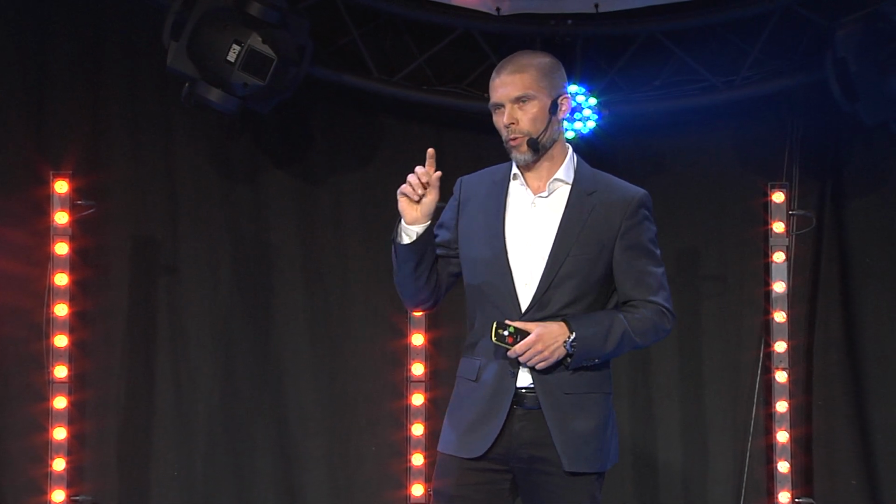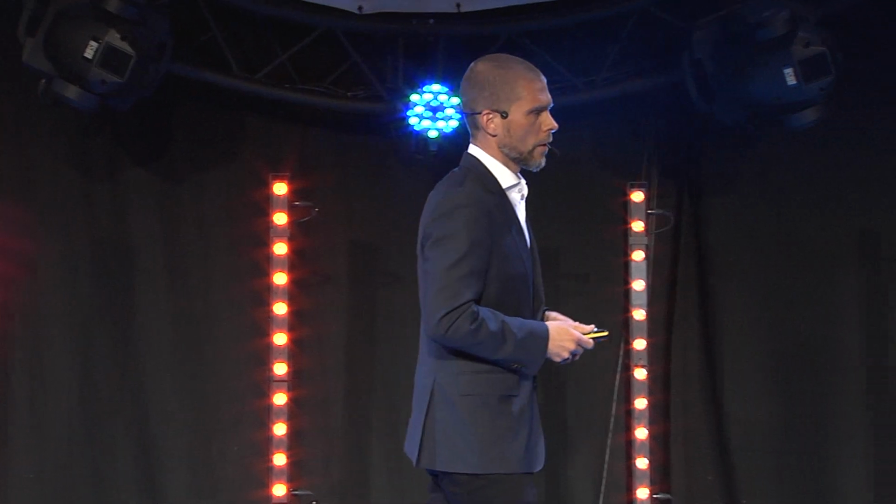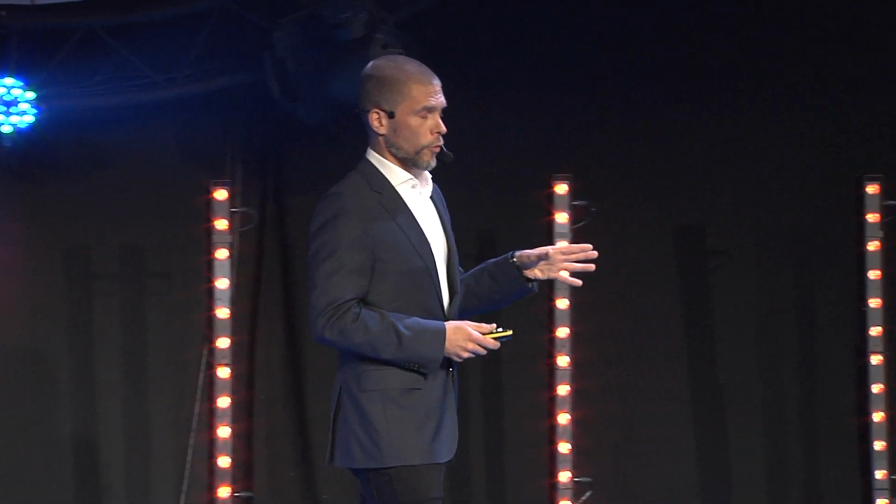But the situation that we were able to avoid is that if you're left with only one fan and that would fail, and you don't know about that situation, you have not only a potential big downtime, but also a serious security risk if you start to get hydrogen into the turbine hall. So very simple, but as an end result, they are now monitoring this in the automation system as well. So this is not going to happen again.